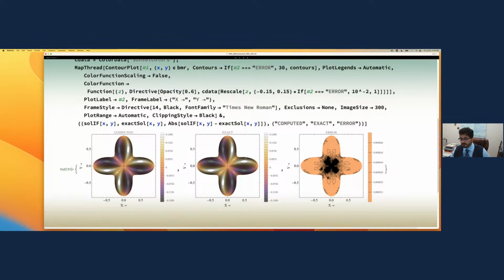So it is a pretty good error. As a matter of fact, I'll show you in the coming slides that the error that you obtain follows exactly the same trend as you would expect from finite difference approximations. So if you were to double the grid size with a fourth order method, your error goes down by a factor of 8. So you do retain all the error convergence advantages that exist with finite difference methods.